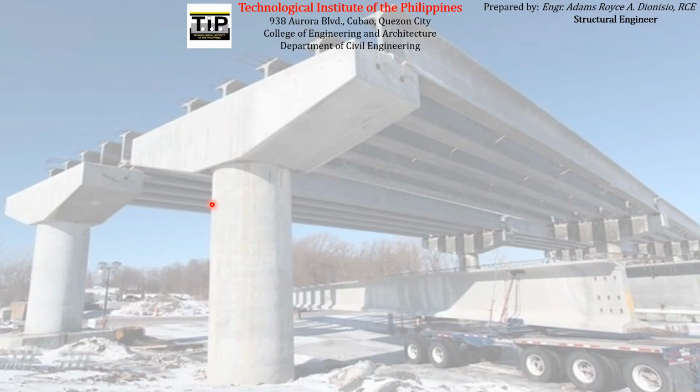So now let's move on to another time-dependent source or cause of prestress loss, which is what we call the shrinkage loss, usually designated as SH. So we know from our previous discussions that shrinkage is the movement of water, specifically moving out from the concrete. That movement of water from the concrete tends to change its volume, thereby producing what we call shrinkage.